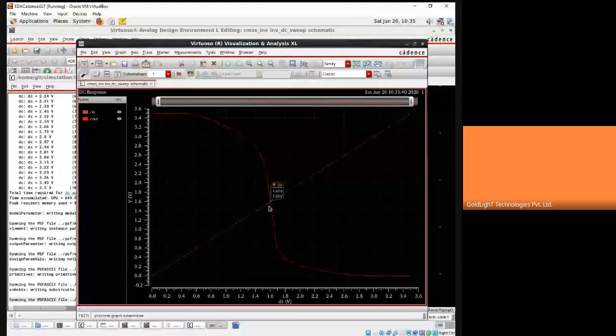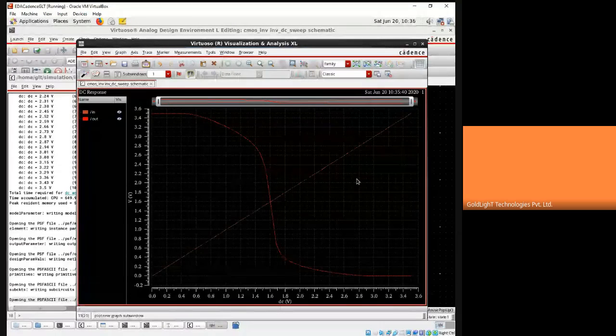Got it? Now, what will happen for multiple values? We can analyze this when we make an ADC or any very big complex circuit. Generally, by using a derivation, finding a proper value will be really very difficult. So for that, in Cadence, a parametric sweep option is available.